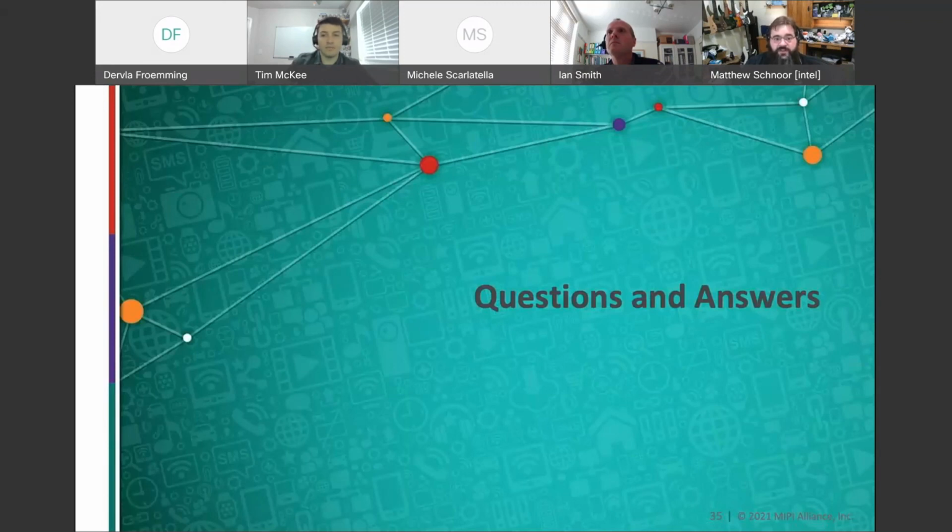If you have multiple targets on a bus, you can send a broadcast RSTACT that says everybody else, no reset, and then send a direct one that says specifically you reset, and then the target reset pattern. So you can do very selective control over which ones of these get reset and which ones don't.